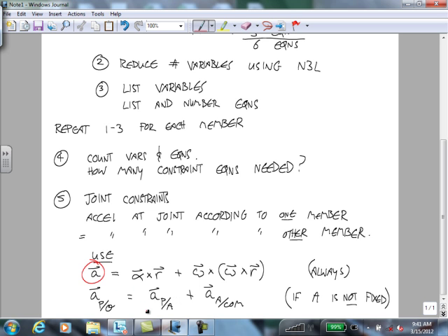Okay, so 2D joint types and the type of loads they apply. So first, by far the most common when you're talking about linkages are pins, but you treat those the same as hinges, and you treat those the same, actually. This one isn't immediately obvious, but contact with friction.